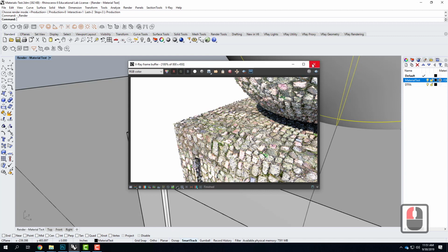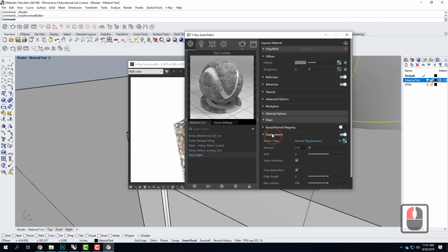So once I've created the material, so in this case I've created this VRay material, we need to find a way to collect it. And as much as I whined and griped and said we really need VRay 3.6, when the Chaos group, the people who write VRay, upgraded to 3.6, they stripped out one absolutely critical, easy command. So we don't have the ability to pack a material like we used to, which is very frustrating to me. So we have to manually pack the material, and I'll walk you through how to do that.